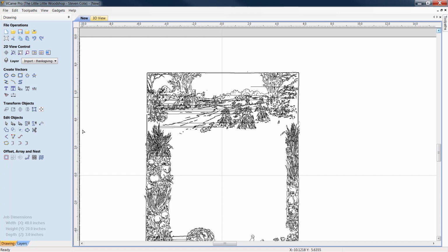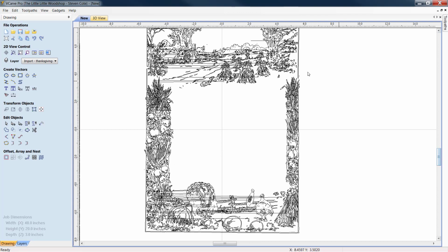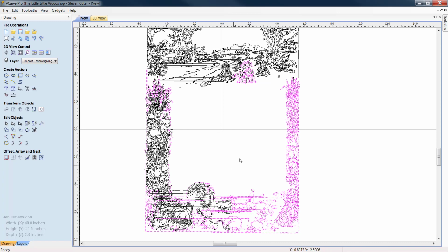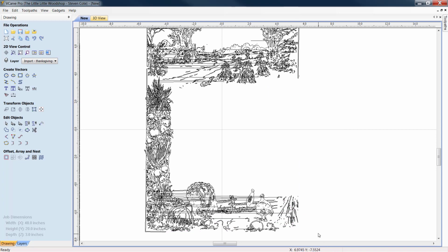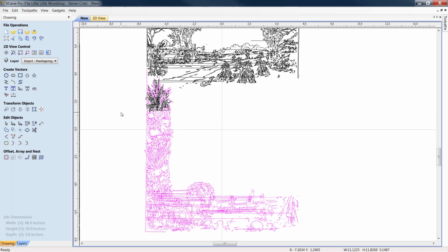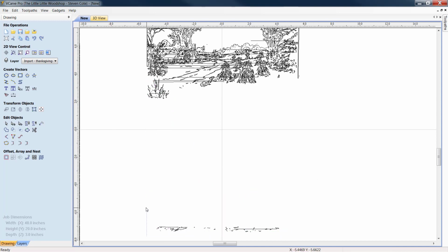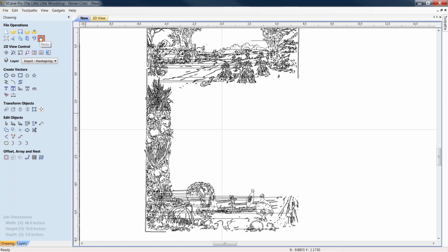I can literally come down here under Edit Objects, Selection Mode. I will come down here now, and I am going to pull as much of this as I can. Whoop! Without taking everything I don't need. Alright, let's delete that. This much is gone. Let's highlight the lower part down here. I'm doing all of this, folks, in Edit Objects, Selection Mode. I just come in, I highlight it holding down my left mouse button. Hit delete. Hit delete. If you take something out you shouldn't, go up here to your undo, your back arrow. It'll put it back. Alright?